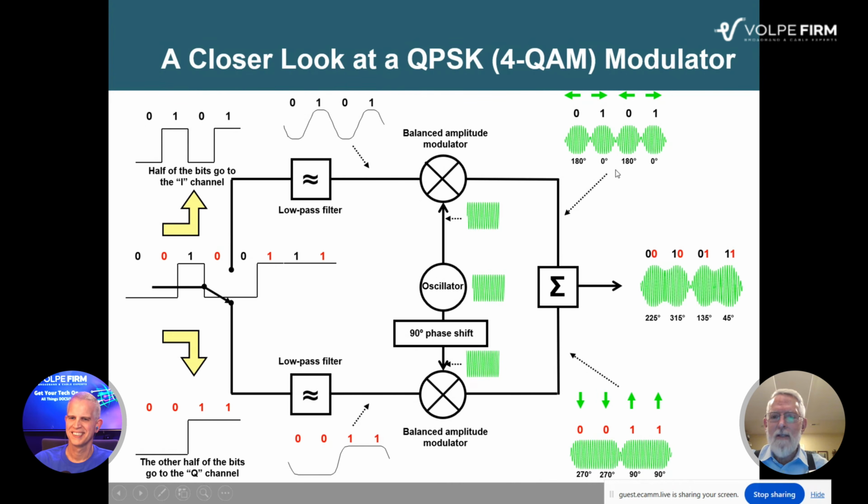Wow. So these two guys, the vector sum, so you just take these arrows and the vector sum looks like that. So assume the magnitude of each arrow is 0.707 volt, then the magnitude of the vector sum would be 1 volt. We're just normalizing it here. And here we're back to our original data stream representation, 00100111. And here there's our original 00100111.